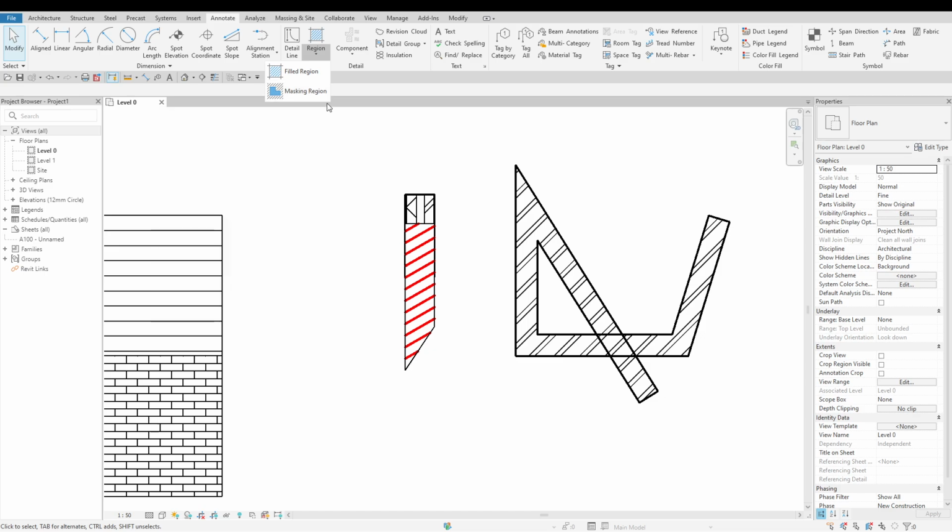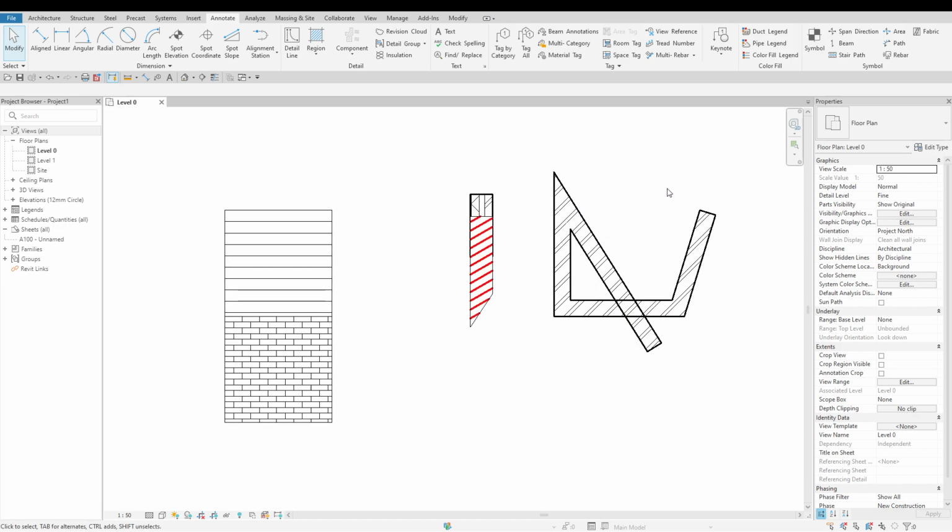They're particularly useful in scenarios like hiding or cleaning up elements in complex views, creating detail families that need to mask other components when loaded into a project, building model families from imported 2D DWG files where the background must be obscured for clarity. Unlike filled regions, masking regions automatically apply a solid white fill and can be placed on top of other elements to provide clean, controlled visibility in sheets or drafting views. We'll explore this tool in more depth in the next episode, including best practices for using masking regions in detail components, families, and imported content workflows.